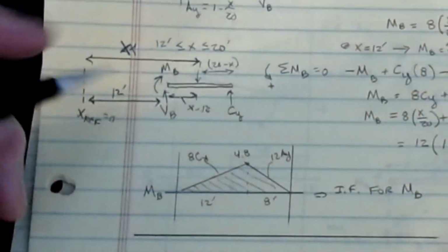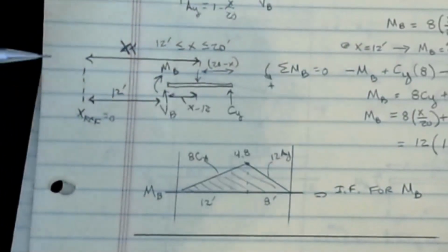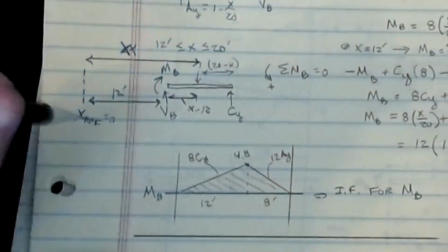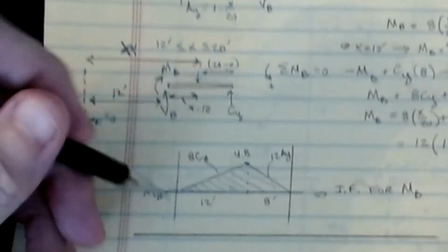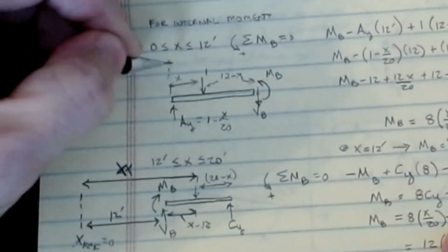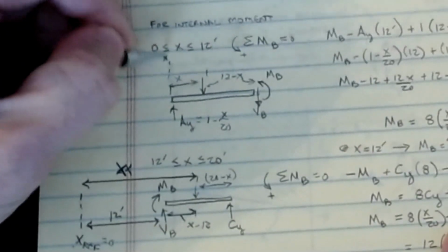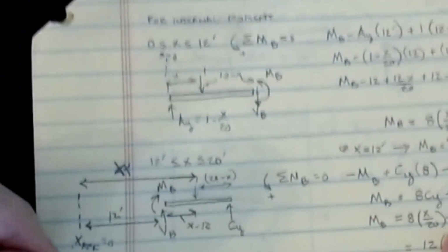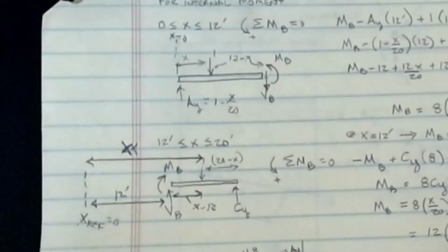And so that would be the way that we would set that up. But again, you choose a reference and you draw it always measured to that reference, and it has to be the same for both. So even on the one that we just did up here, that was my reference. And notice that x was measured here. This was x equals 0. This guy is still x equals 0, and so forth. So you got to measure relative to each other to get that to work.